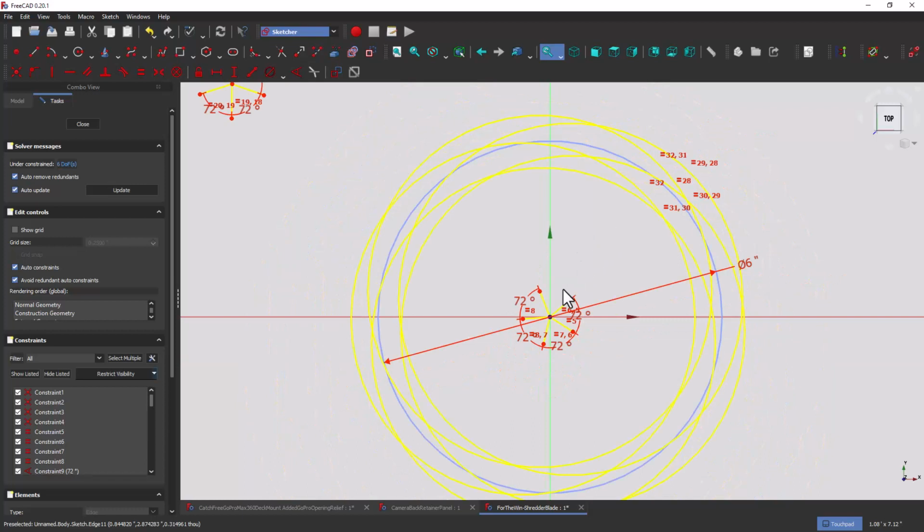So what I want to do is I want to lock this in. I'm going to give the dimensions. Now remember we said that all of these are going to be equal. You put the constraint that they're all equal. So now I am going to let it tell me how long that is. I'm not going to put a number in there. I'm going to say, let it tell me how long that is.